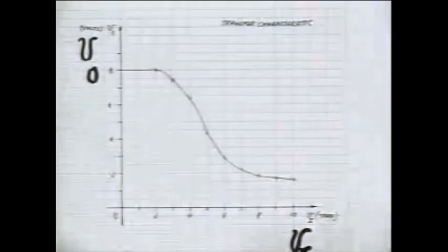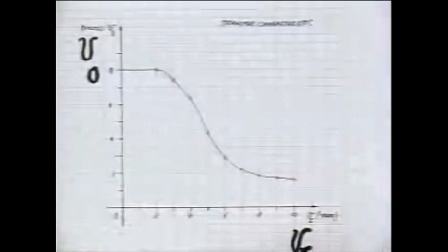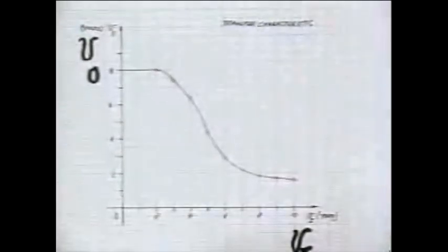And for our purposes at this time in the subject, this control is being exercised with the expenditure of no energy. That is, the gate current is 0. You can control the gate to source voltage with no expenditure of power at the gate to source terminals, 0 current. Here we are controlling the voltage across the resistor, the load resistor, and that is clearly dissipating power in the load resistor.